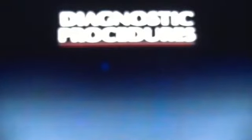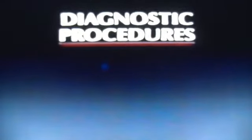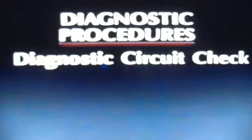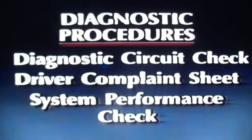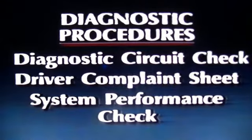The General Motors diagnostic procedures consist of 3 phases: diagnostic circuit check, driver complaint sheet, and system performance check. This little chart gives you a preview of what we'll be covering. Step 1, the diagnostic circuit check, means you go to the computer and see if there are any trouble codes stored in its memory. If there are, the ECM will give you a trouble code number. This number matches a chart with specific instructions for correctly identifying the problem.